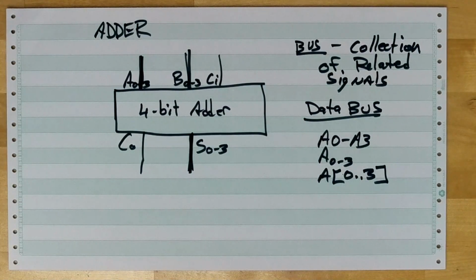One closing thought on the way out the door here. What do you think it would be like to try and express the carry out using Boolean algebra for just this 4-bit adder? What do you think it would be like to express it on a 64-bit adder? Think of the number of variables and operators in that expression, because it obviously involves the carry in, the 64 A bus values, the 64 B bus values, and all those carries.